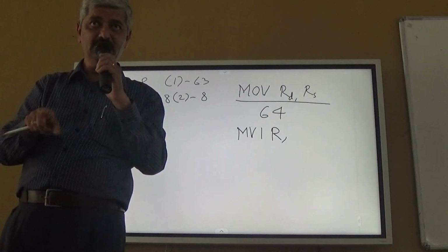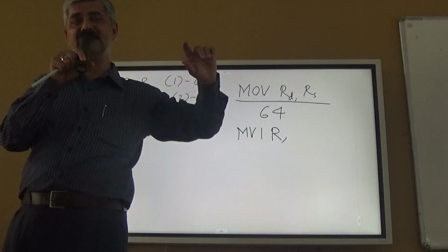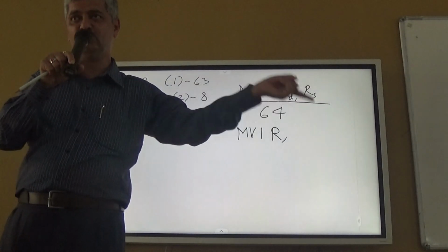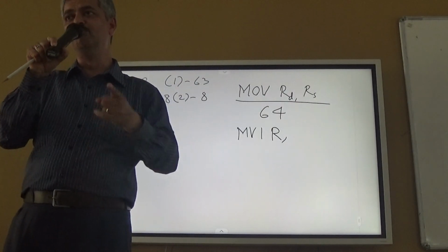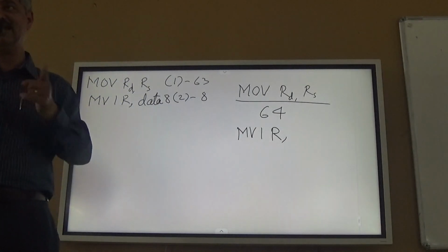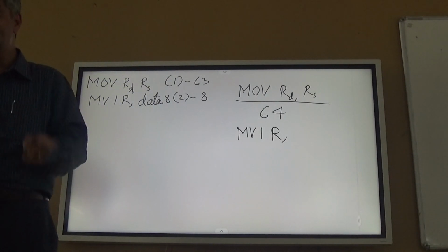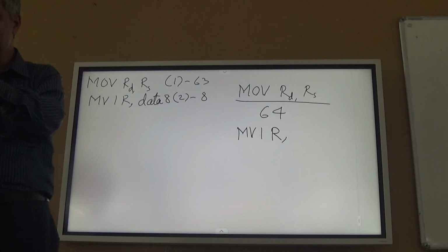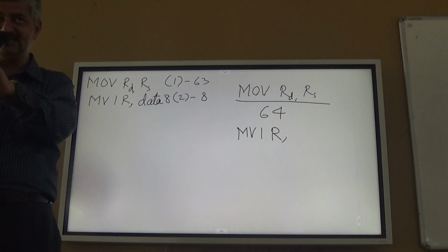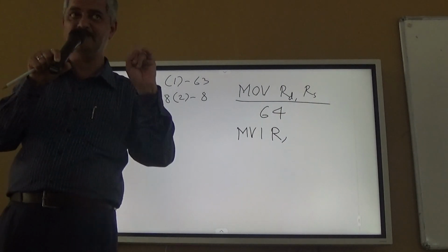What do we want? We want the contents of memory location 5000 to be brought to accumulator. So the MOV A, M instruction can do that if and only if the HL pair contains H contains 50, L contains 00.